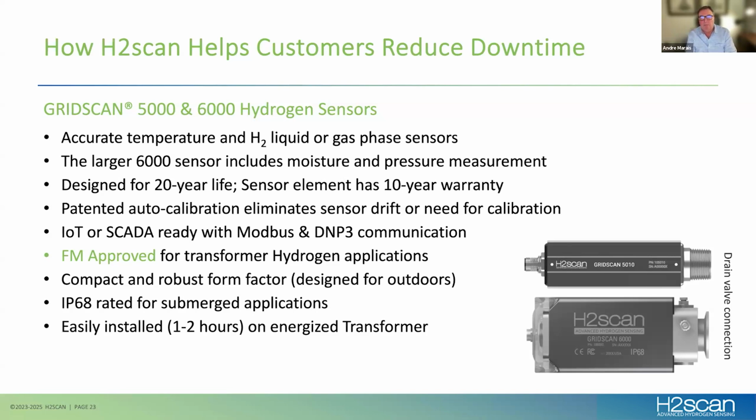It looks at the drift, and when it sees a certain amount of movement, it will self-trigger the auto calibration process. If it's not successful, these sensors have diagnostic registers, and it will notify you through the diagnostic register that there's an alarm. I have personally never heard of it fail, but should it happen, there's a Modbus or DNP register where we pick up the diagnostic information. And you'd be alerted that way.